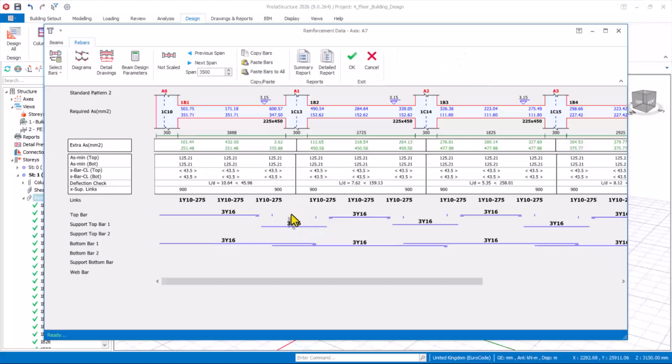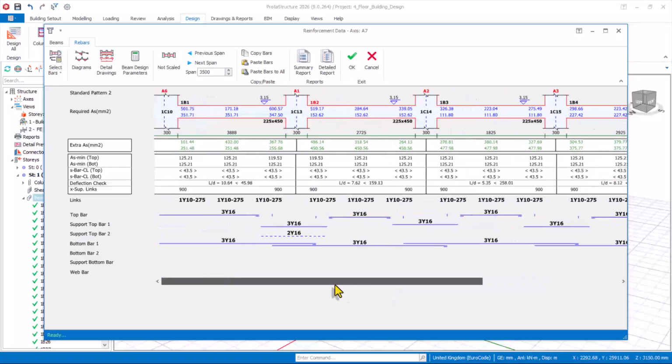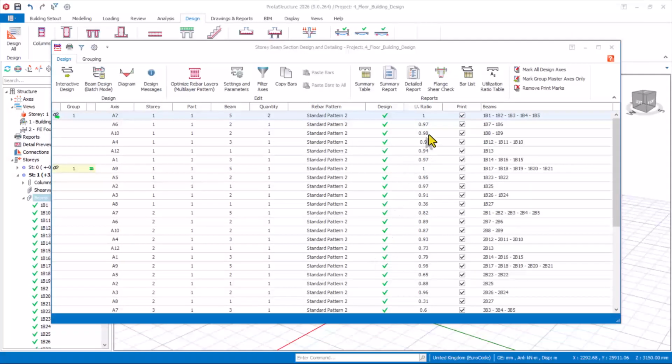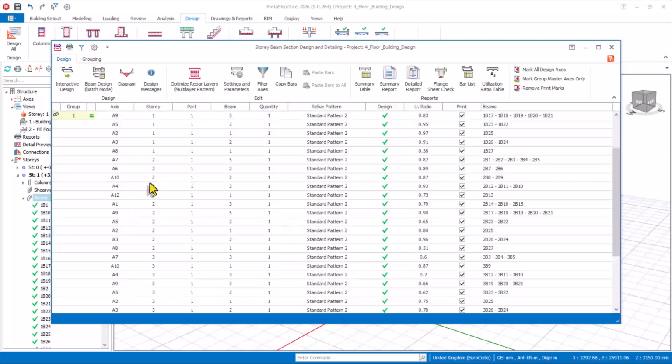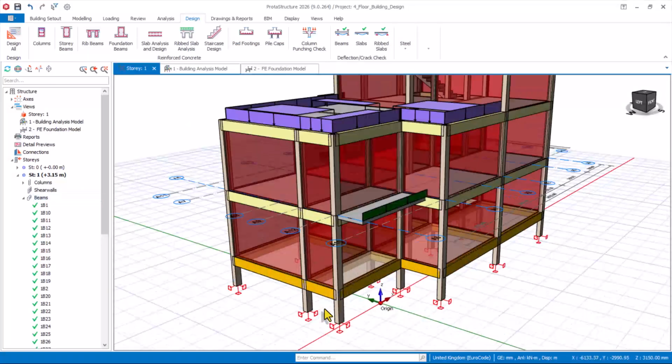So what you need to do is add a support reinforcement here. You can add 216 as a support reinforcement to correct that. Let's check the area. Your attention should be on the area of reinforcement. This is good. Now click on the OK. Let's see what we'll get. See, we have 0.83 as U ratio. This is fine. So what I've done now is what you're going to do to almost all the beams, interacting with all of the beams to ensure that you have an economical and safe design. After which you click on the close options. We are done with the beams.